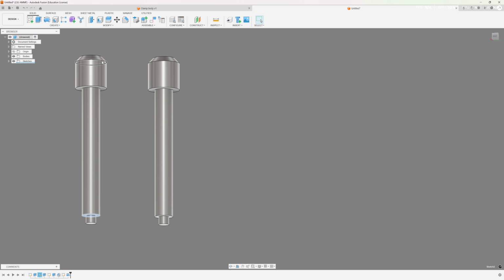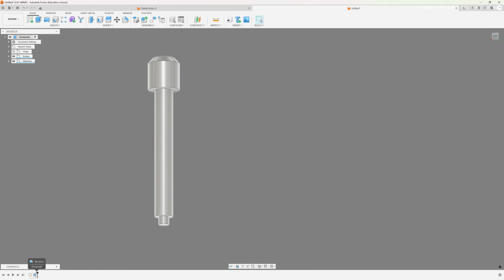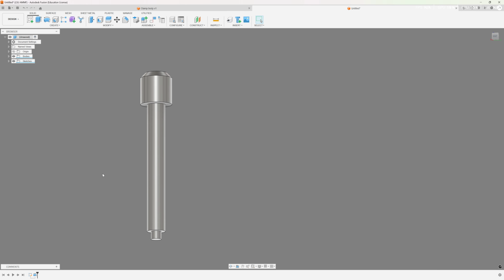So while this stacking of extrusions is a simpler thing to do, the revolve function is going to be a whole lot more beneficial later down the road. So with all that being said, I'm going to select in my workflow down here and just hit delete, and delete all of that work from that other pin because I don't really need it. I have this pin right here.